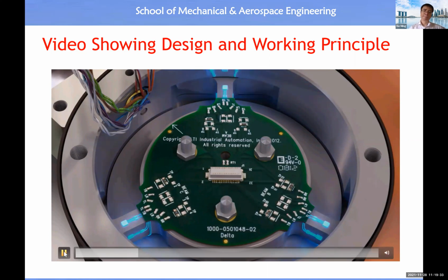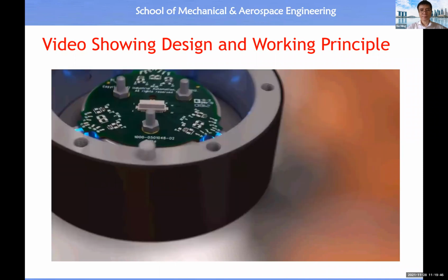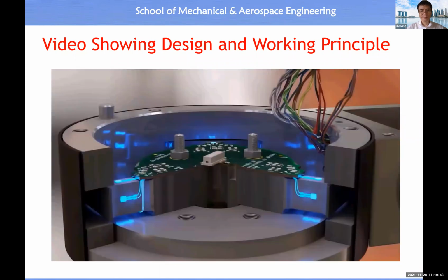Form half bridges. The output of the transducer is 6 channels of strain gauge voltages. The output is digitized and then converted to force and torques through a matrix calculation. ATI uses very sensitive silicon strain gauges to maximize gain, greatly reduce noise.